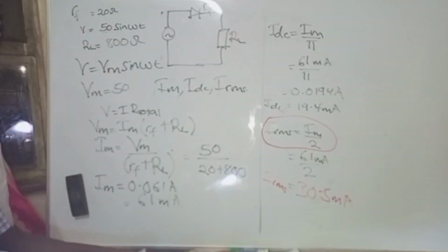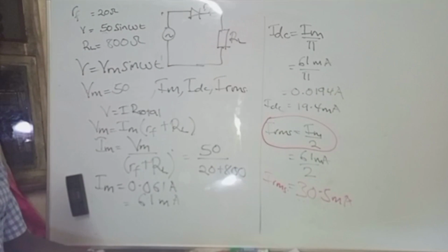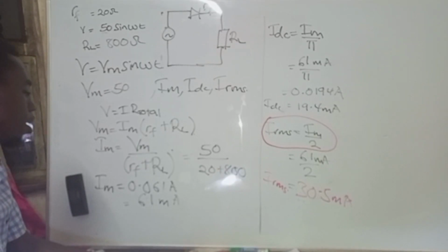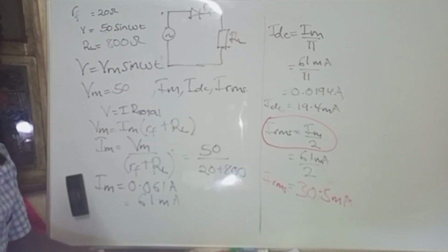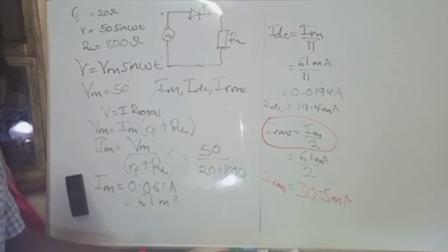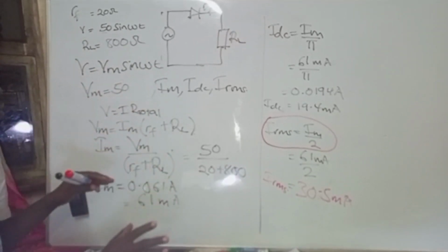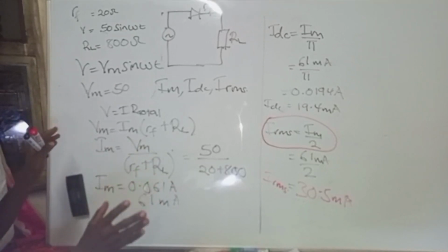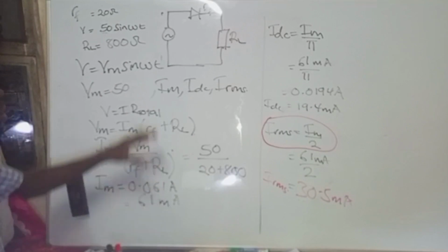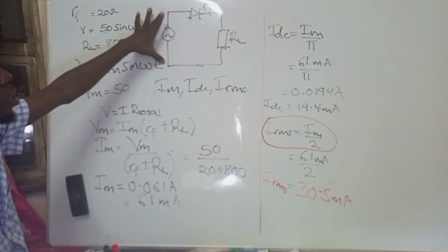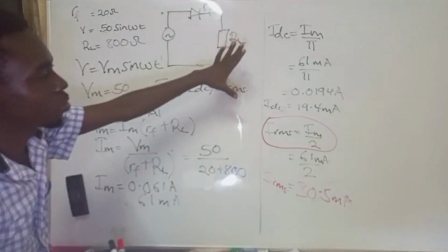So given this scenario that we have our root mean square value of current, we have our DC voltage, we have our DC current, the next part wants us to find the AC power input and DC power output. Here again we need to note, where does AC power input occur and where does DC power output occur? The AC power input occurs before this whole cycle.